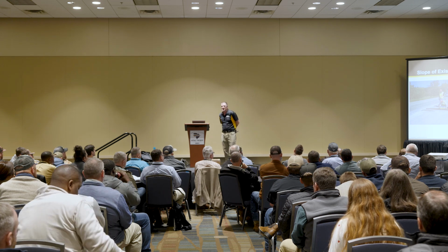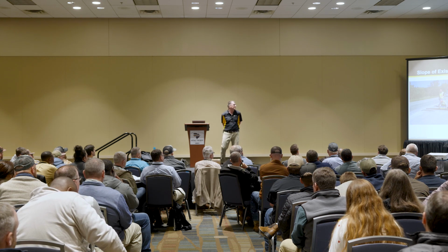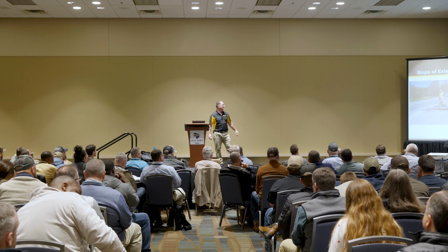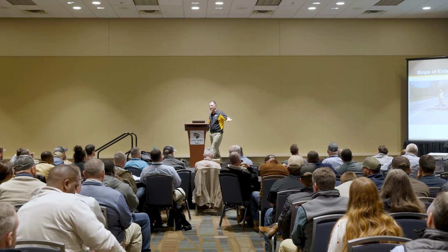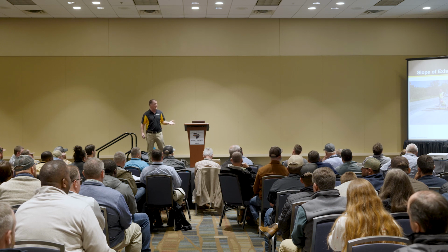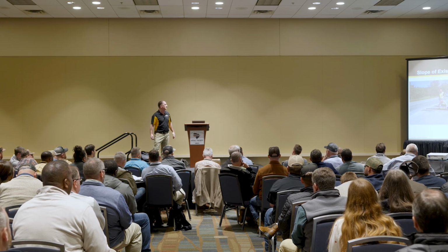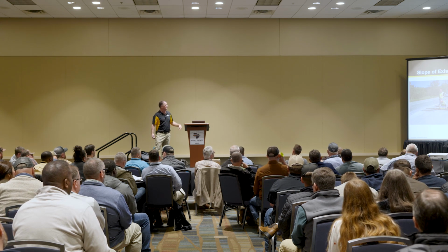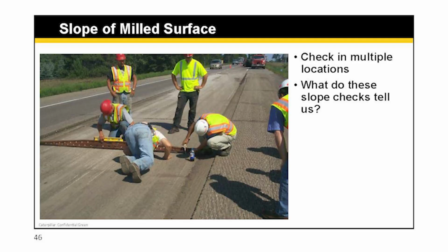Kind of got our hands tied a little bit, don't we, on that situation. Might be able to level it, put a bit of level course in there. Probably not going to get the mill to come back there and do it unless you're catching them on the day they're there. But it can create problems for us, right? And you want to check in multiple spots. So you're going to check that. That's the quality control. Do we do a good job on QC on checking our grade after milling?